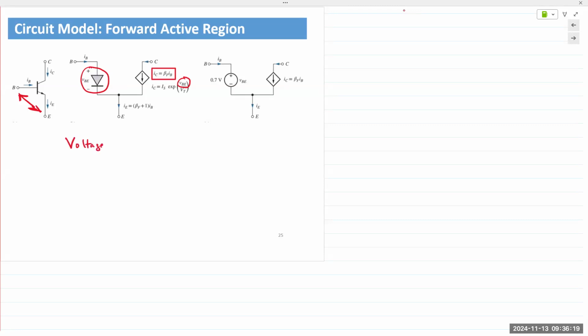Using this model, we can describe the BJT as a voltage controlled current source. I'm assuming at this point that you all, if you don't remember, at least came across this in 113 last year. The reason it is a current source is because the output current IC is constant or near constant, a flat line, and IC is controlled by the input voltage VBE on the input side.